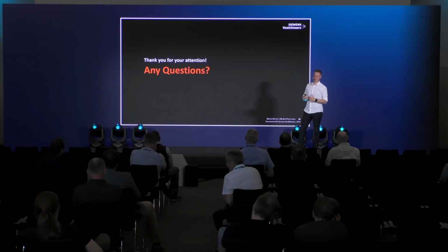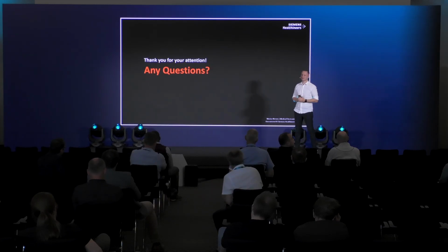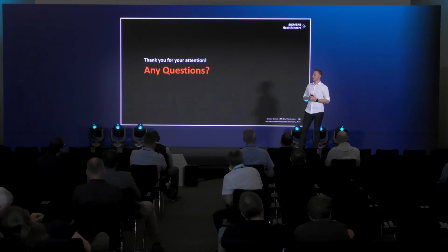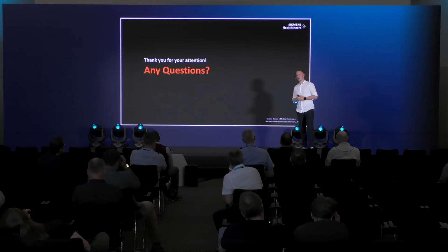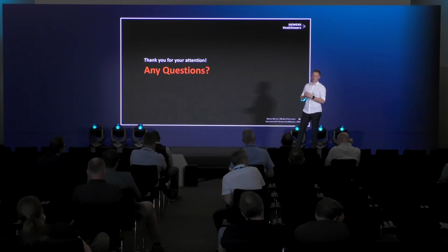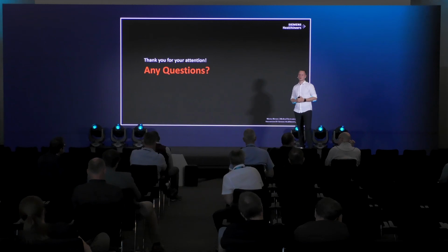If you have large boards, FPGAs, large BGAs, then it's always a trade-off. For example, I know the 100 ohms are quite difficult to achieve, because you have anti-pads that are huge most of the time, so it's always a trade-off.